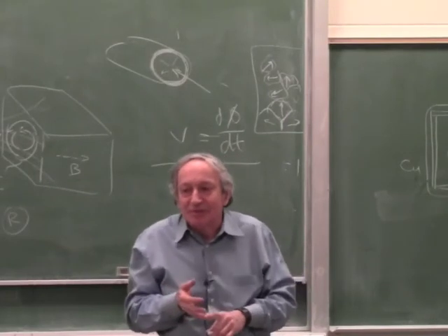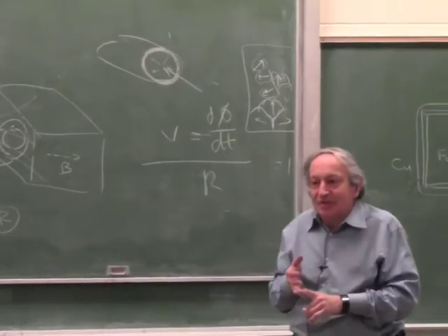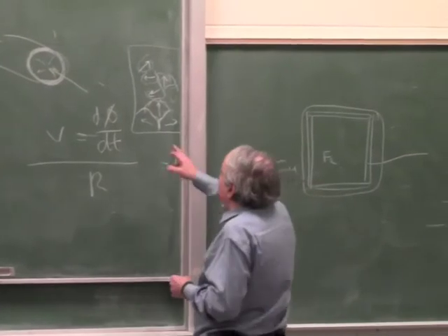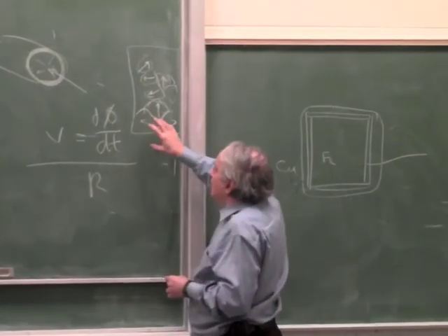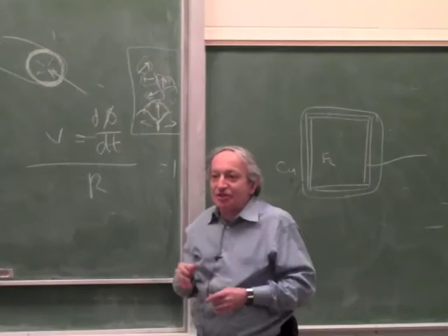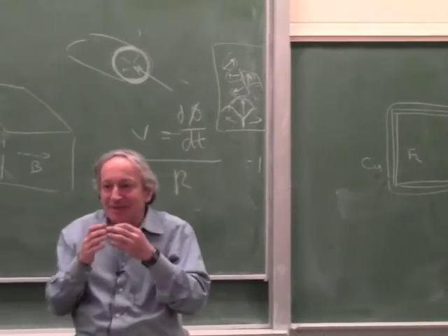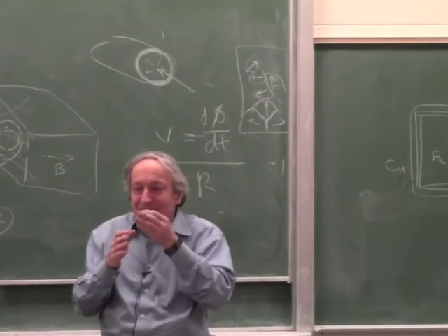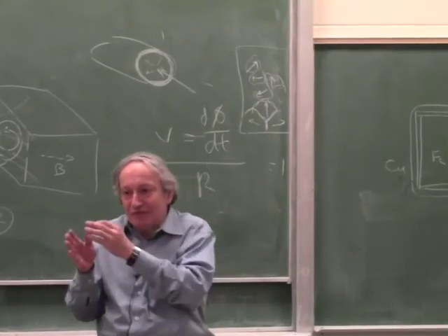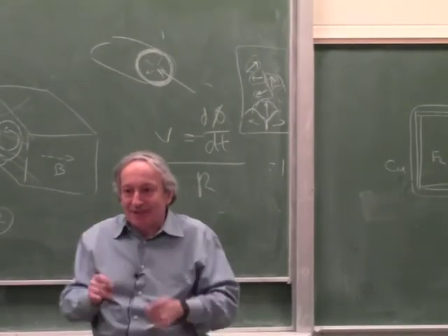So there is some physical movement, but what really happens, the most noticeable effect, is that the boundaries of these domains change and the orientation of the domains changes. It doesn't mean the domain is physically rotating, but the boundaries, where the magnetic lines separate, shift, and they all line up.